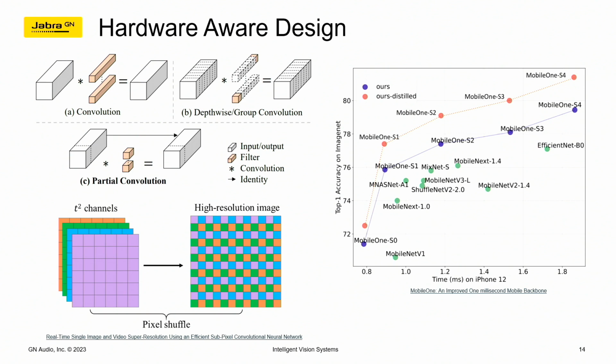Next, hardware-aware design, which is very, very important, because the end product is a combination of hardware and software. They both go hand in hand. It's not either of those. So basically what you can do here is, if you know your hardware well, if you know what layers are supported, what's the latency of your layers, or different kinds of kernel operations, you can choose those layers based upon that. If your hardware has been defined before, then you know what your memory budget is, you know what your latency budget is depending upon the applications. So you can choose the layers accordingly.